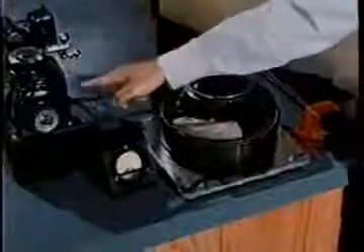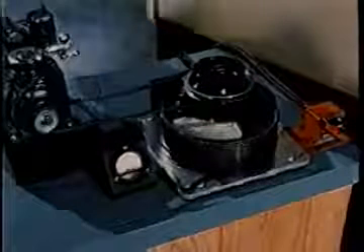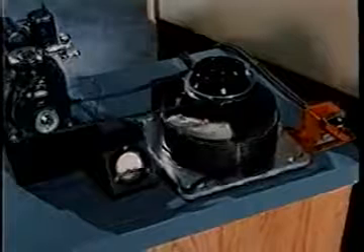Let us now look quantitatively. We measure the height of the waves using a capacitive transducer and record the wave height and airspeed on this pen recorder. Now the wave maker is going at a constant frequency and amplitude. Using a motor drive on the airspeed control, we start the tunnel and then increase the airspeed slowly. We can speed this up cinematographically.